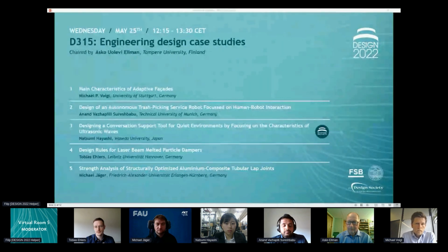And I see the second question in the chat. That is a strength and stiffness question, because when I have one big cavity, the stiffness of the beam is not so good. So I think it is better for stiffness and damping design that you put more than one cavity in the beam, maybe 3 or 4, and then we have a good compromise of a high damping and a high stiffness and a high strength. So I would recommend this.